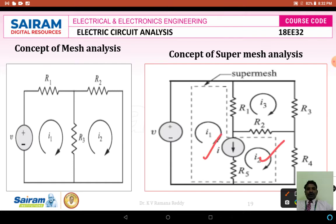The I1 current is in the direction of the current source, so I can give priority to I1. I can write the equation as loop 1 current minus loop 2 current: I1 minus I2 is equal to the current source I.